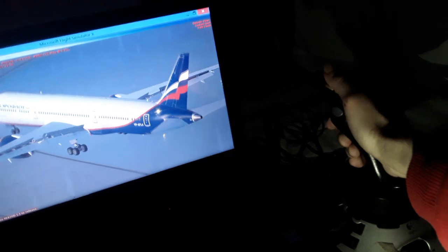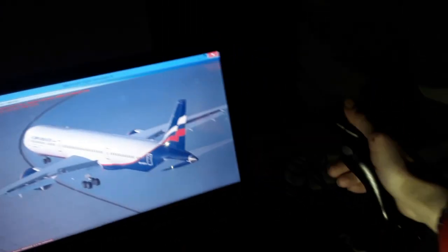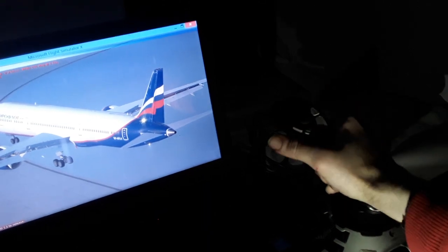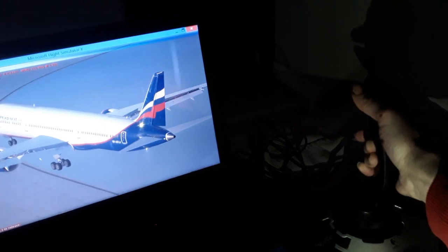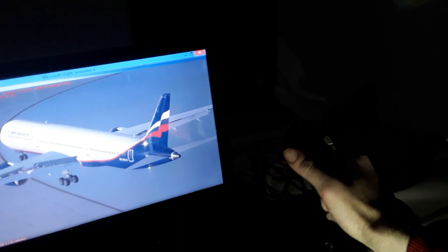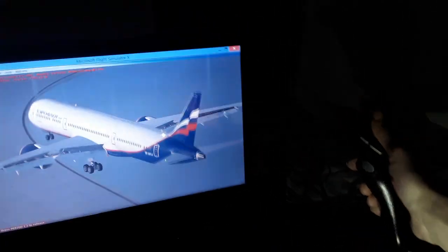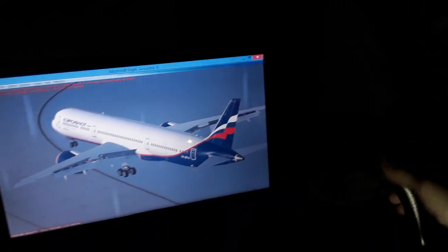We can climb and we can descend the aircraft around the lateral axis from one wingtip to the other wingtip. We can climb and we can descend like this. We can make turns to the right and turns to the left. In flight we can bank roll left and right like this. So to make a bank roll we use the longitudinal axis that traverses from nose to tail through the center of gravity, as you can see.